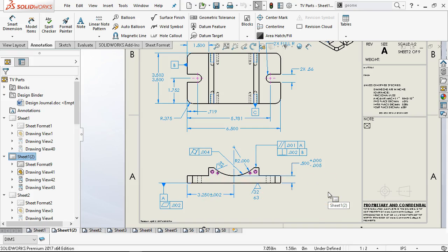All right, so start thinking. It's very easy to overthink, and you want to put more. Less is more. I don't know how else to put it. Try not to overcomplicate it to where you're having to follow through all of these datums, all of these feature control frames to get to what it is you really want, which is just the part.